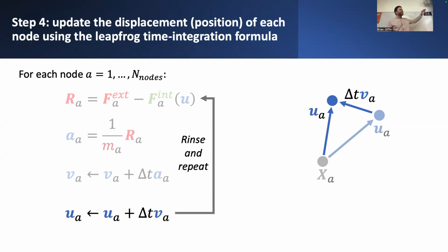this method. And really the advantage of this method is the fact that you can handle nonlinear behavior without having to do any kind of nonlinear iteration at all. So if you have a ton of nonlinear behavior going on, large deformations or nonlinear material behavior, explicit dynamics is an excellent option to work around a lot of those complications because you don't have to deal with convergence issues or setting convergence tolerance values. It just works. It just goes. It gives you a solution. You don't have to worry about any of those details. You just need to make sure you take a smaller time step size.